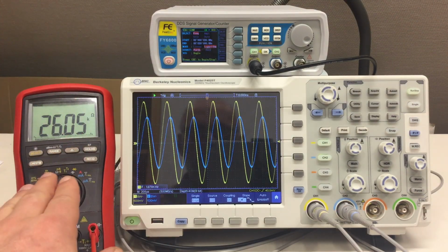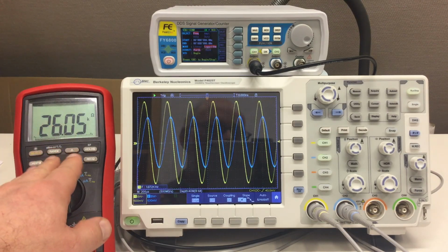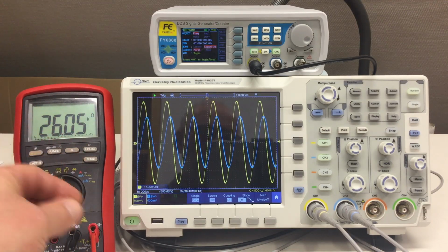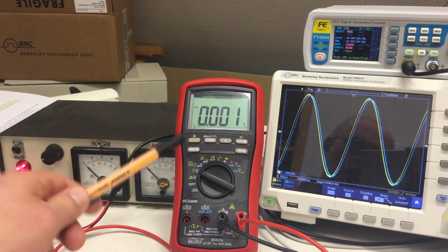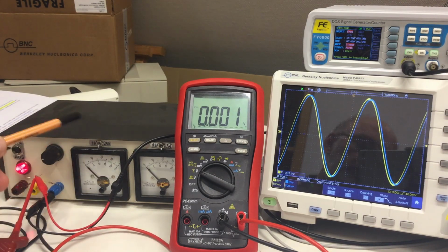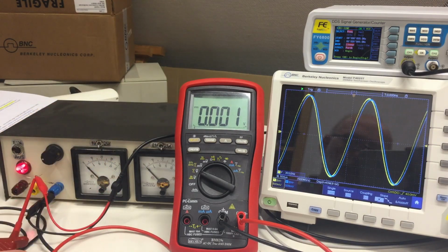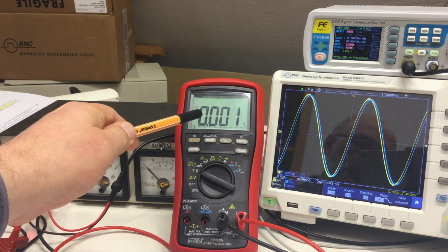And another tidbit of information, the input resistance of the VCO input at the back is 26 kilo ohms, so not really high impedance, but also not 50 ohm terminated. So what I'm doing now is I'm feeding the VCO input via a little voltage divider here a defined voltage from my power source, which I display here, and I will write down the output frequency at each voltage.